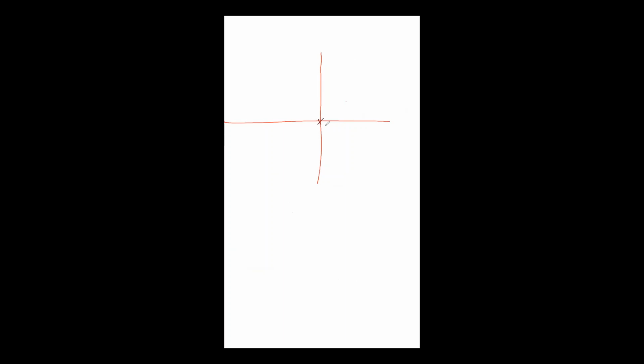One pole is at origin, another pole is at minus 4. Let us suppose this is minus 2. This is my part of root locus we have seen, because the total number of poles to the right side of this pole is odd. This is starting from here, this is starting from here. This is k is equal to 0 here, k is equal to 0 here. The branch is going downwards, this is going upwards.